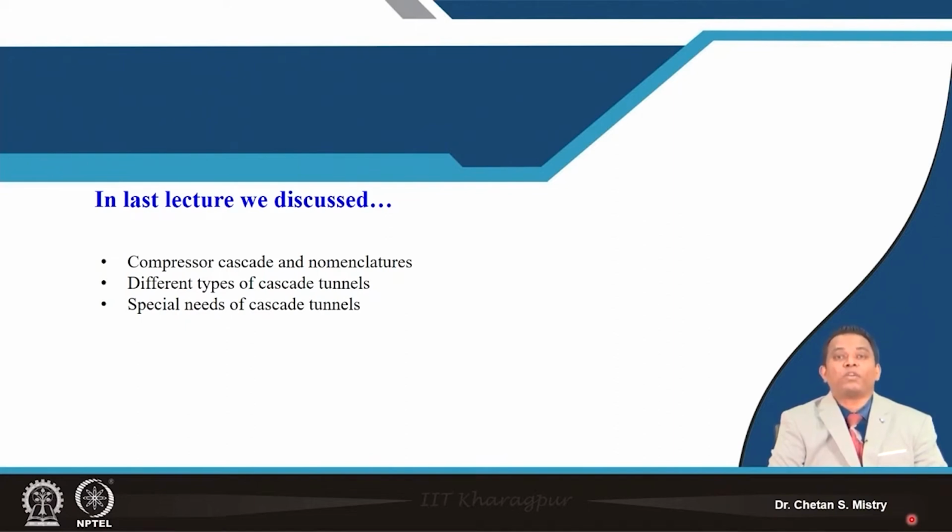So what is happening on the blade surface is of our interest. In the same way, how pressure is distributed on the pressure surface and suction surface gives me the lift coefficient, or CL, and we have correlated that lift coefficient with the pressurizing capacity of that particular aerofoil.